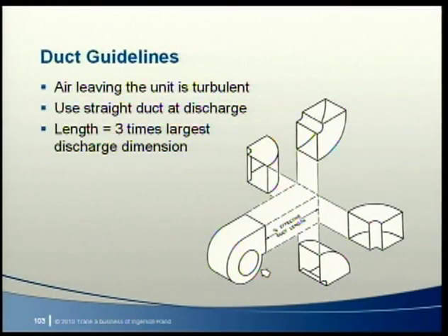As I mentioned, we don't have modeling tools that show the acoustical impact of these unique duct designs, but there are some general guidelines that will help prevent installation-related problems. First, assume that the air leaving the air handler has an uneven velocity profile and needs at least 3 times the largest discharge opening dimension of straight duct to stabilize.